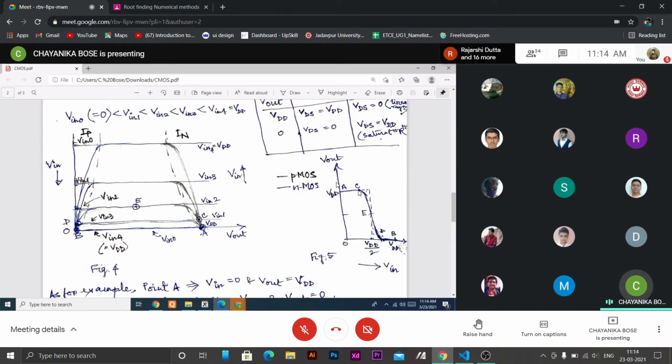Desired value of output will be maintained still then, because for 0 it should be 1, and it remains 1 up to this maximum of 4 volt noise, in presence of this noise. So it gives some noise margin, noise immunity to the circuit, and this is the noise margin: the maximum amplitude of noise that the device can safely handle and will behave properly, as it should do in absence of noise. যেটা expected সেই ভ্যালুই দিচ্ছে in presence of this noise.